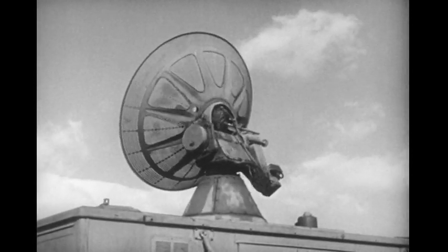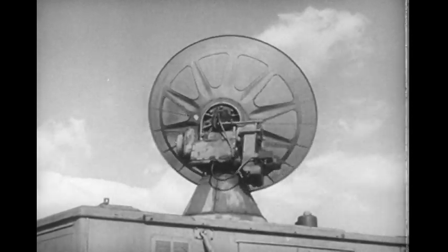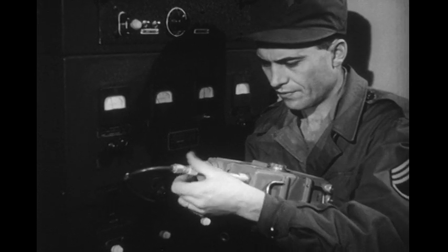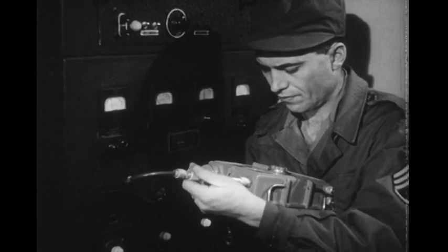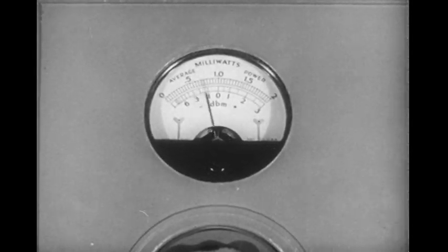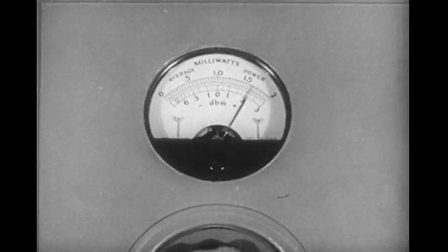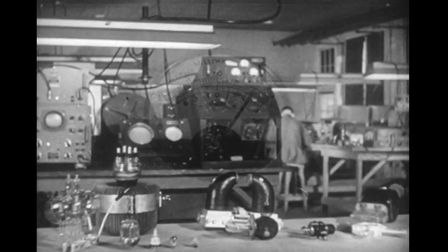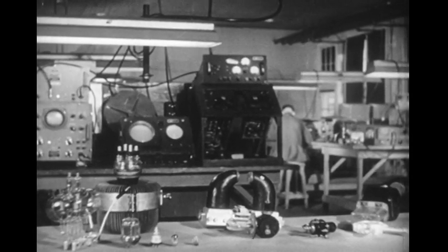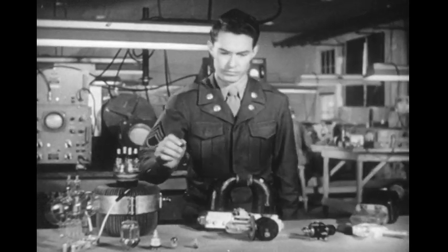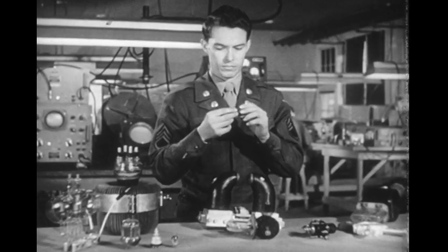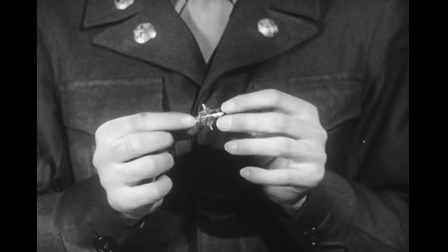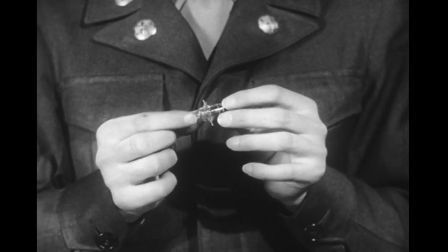In order to obtain the ranges desired for most tactical purposes, the radar transmitter must emit radiations of rather high peak power, from 25 to 200 kilowatts, and in some cases up to 500 kilowatts. Such power cannot be generated in the usual triode oscillators. At 10 centimeters or less, the electron transit time is so small that the tube cannot be made large enough to deliver more than a fraction of the required power.